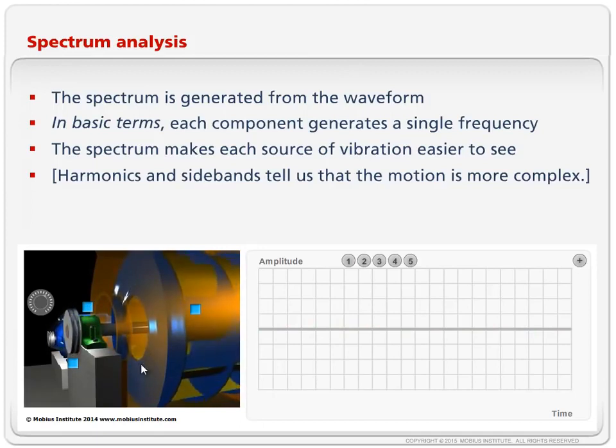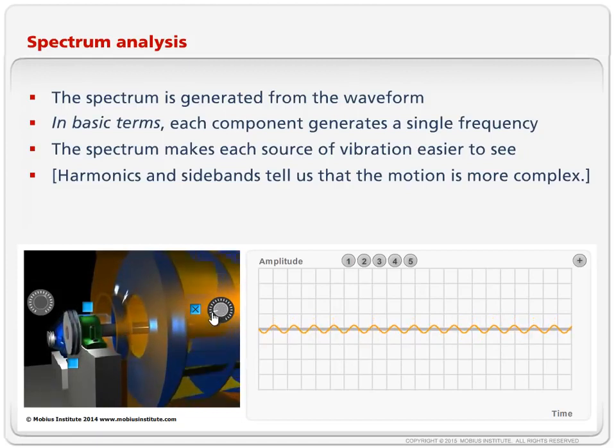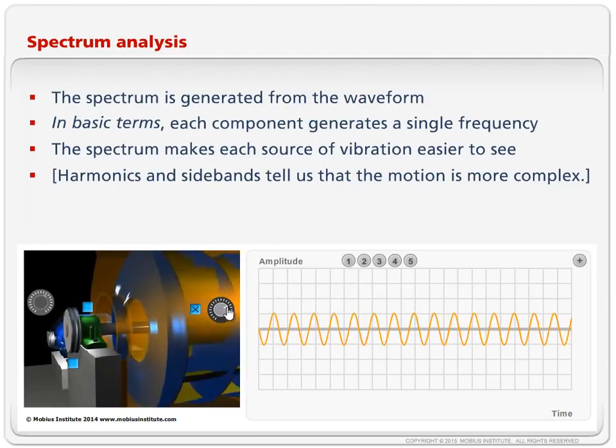I've got 10 blades on this fan. And if the air flowed through those blades nice and uniformly, I might not get very much vibration. But if there wasn't as much uniformity, if the blades were bent, let's say, or a number of other potential problems, I get more vibration. But this is a different frequency from the two we've seen before.